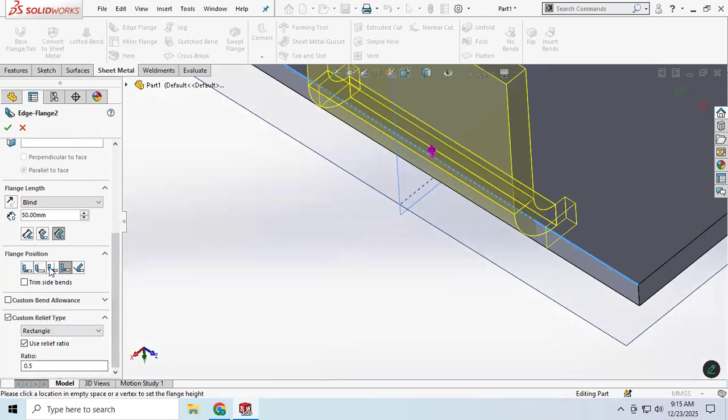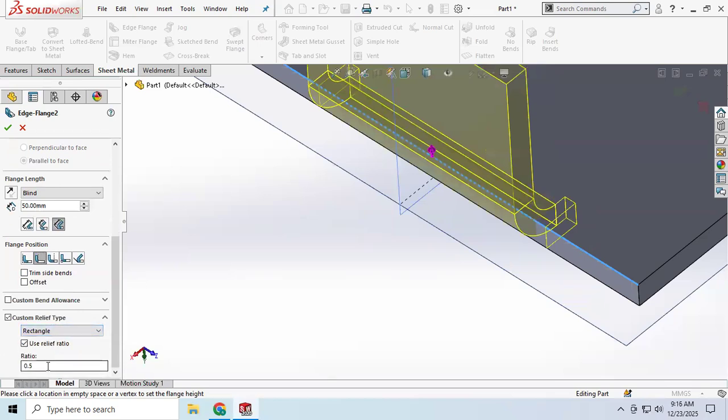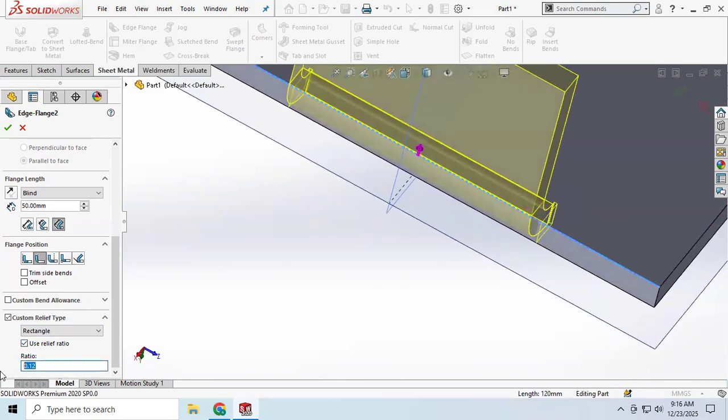So there, what I do? Here we have the other option, outboard. And then here we have the ratio, 1 to 5 ratio. If you click on the ratio and then click on 0.1, your ratio will decrease right here. If you click on the 0 point, it will lie between 0 to 1. If you click in this, it will increase your ratio. So I just use 0.5.